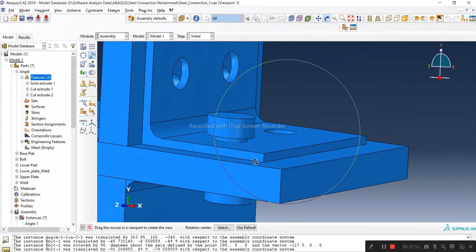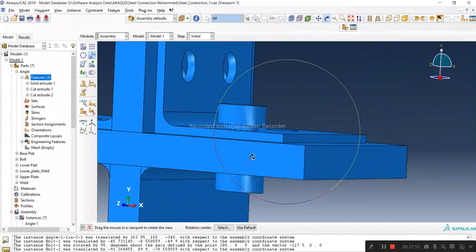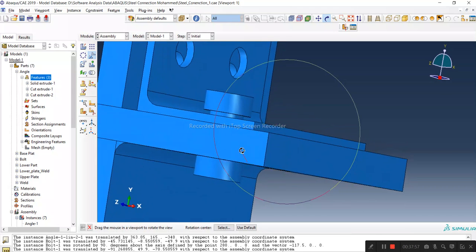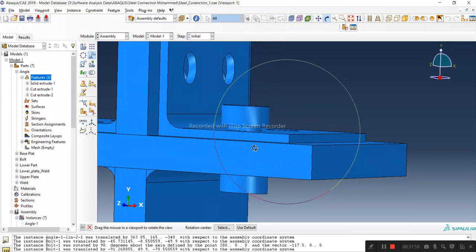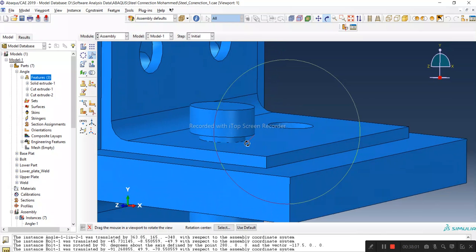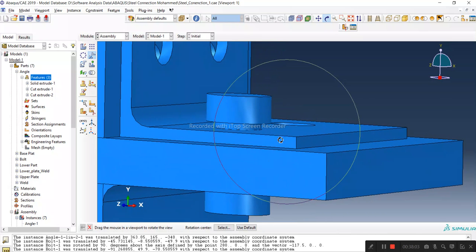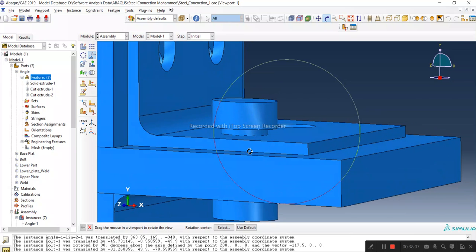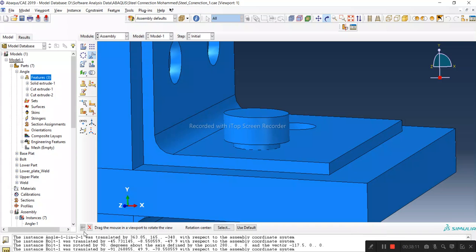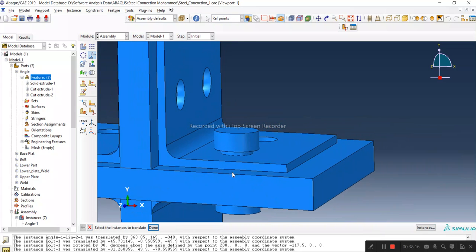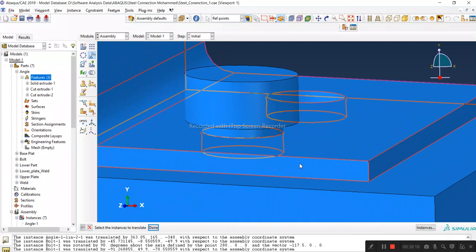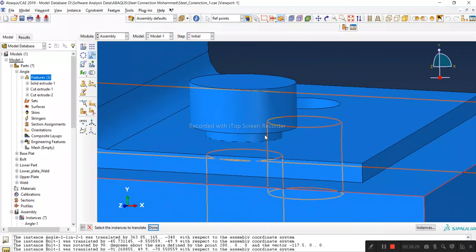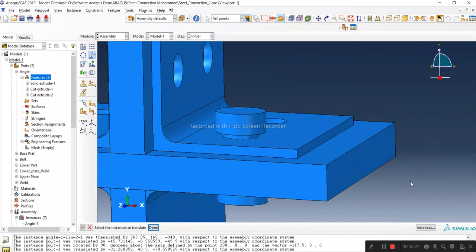Oh no, it's not exactly what we wanted. So we wanted this to be, or in fact we are not sure whether the thickness of the bolt is equal to the thickness of these two plates. Perhaps this is accurate, but the thickness of these plates needs to be changed. I have a feeling that I might have this thickness wrong. I need to check it again. Probably this is not 6, this is 10 mm thickness, so that will make this bolt accurate.